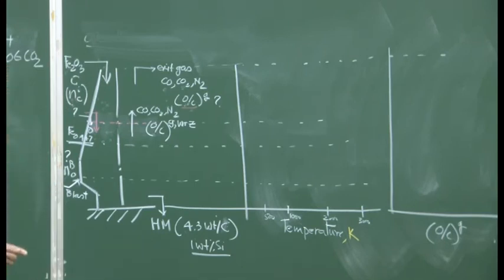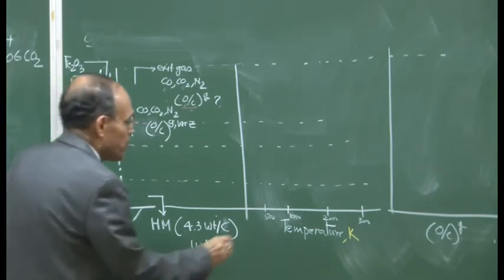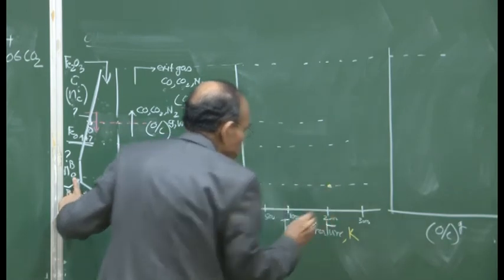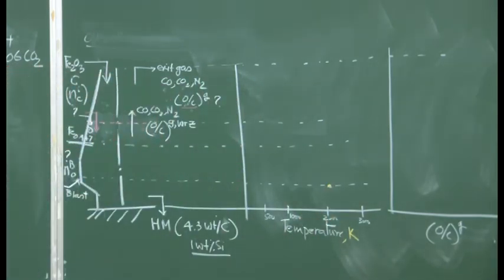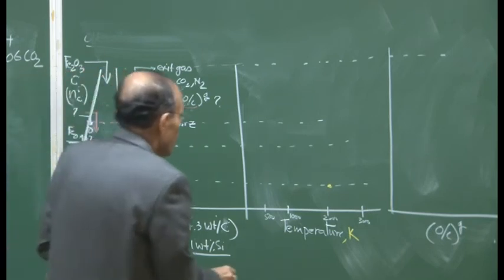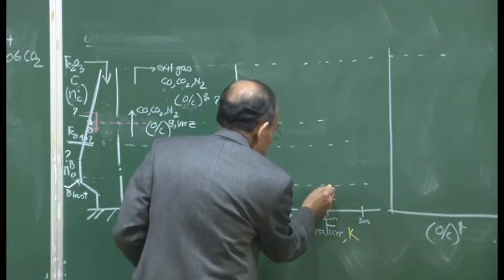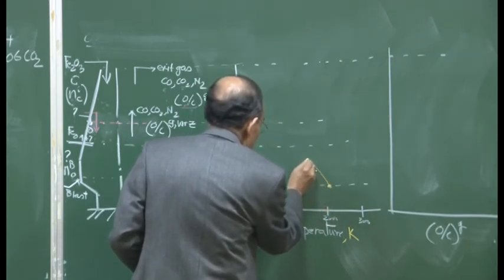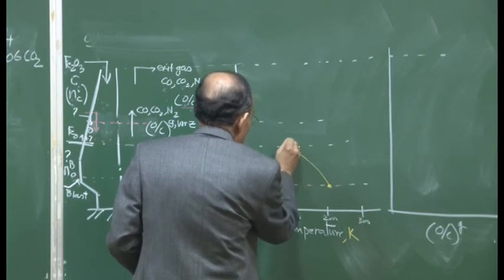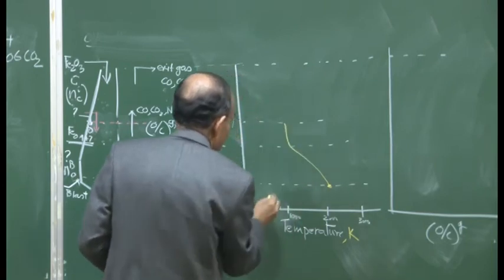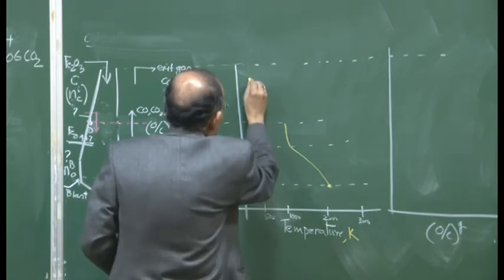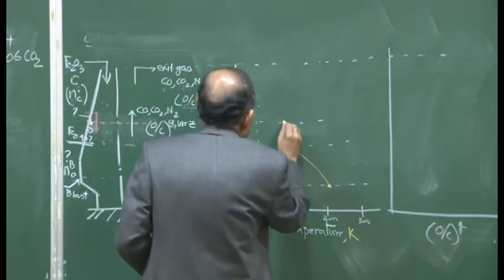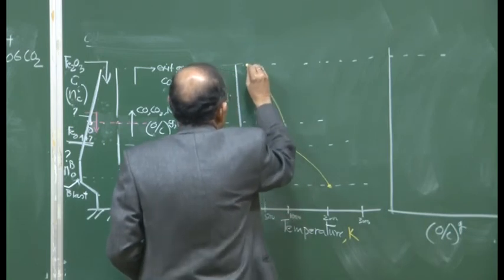We look at the gas temperature first. The gas is at a very high temperature. So, the gas temperature here is 2100 or 2200 Kelvin, okay, at the tuyere region. And now, as the gas is ascending, its temperature is going down, it is yielding its heat. So, the temperature decreases and it goes something like this. And the gas, as I have indicated, could be somewhere around 500 degrees centigrade, and that is how the gas temperature goes.